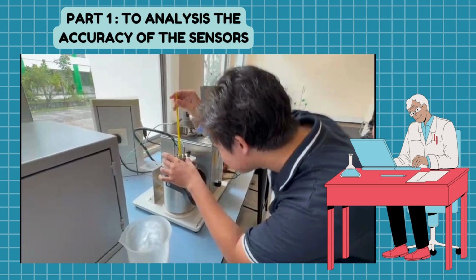First, prepare standard temperature reference points. Use an ice bath at 0 degrees Celsius and boiling water at 100 degrees Celsius as reference temperatures, and ambient air at 22 degrees Celsius using a control water bath or heater.